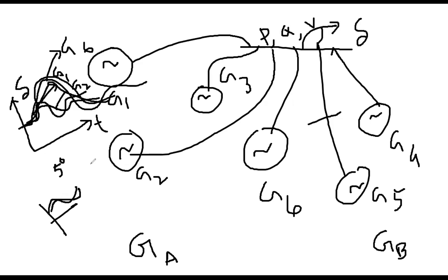So the definition of coherent is generators which swing and run almost together, keeping the power angle difference within 5 degrees. Those you can treat as a coherent group.